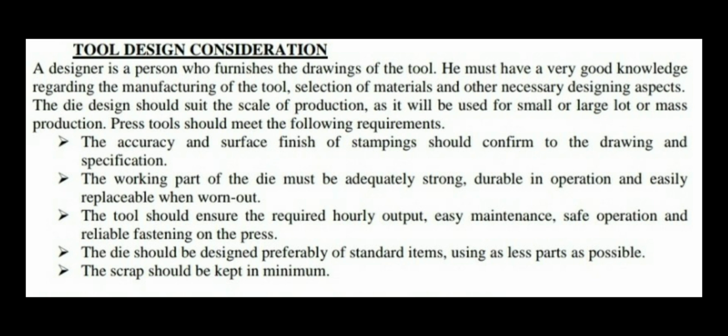What is required from that press tool? Accuracy. The accuracy and surface finish of the stamping should conform to the drawing and other specifications. The working part of the die must be adequately strong, durable in operation, and easily replaceable when worn out. The tool should ensure the required hourly output. It should have good productivity, easy maintenance, safe operation, and reliable fastening on the press.